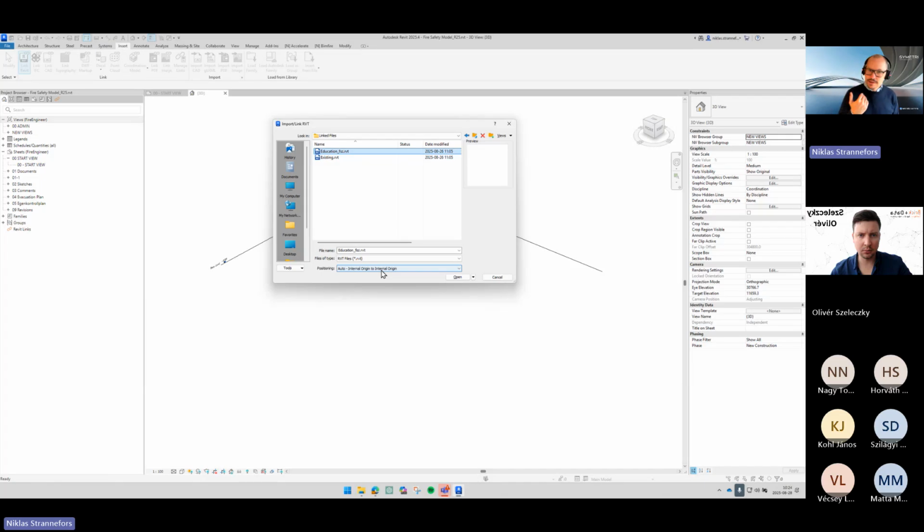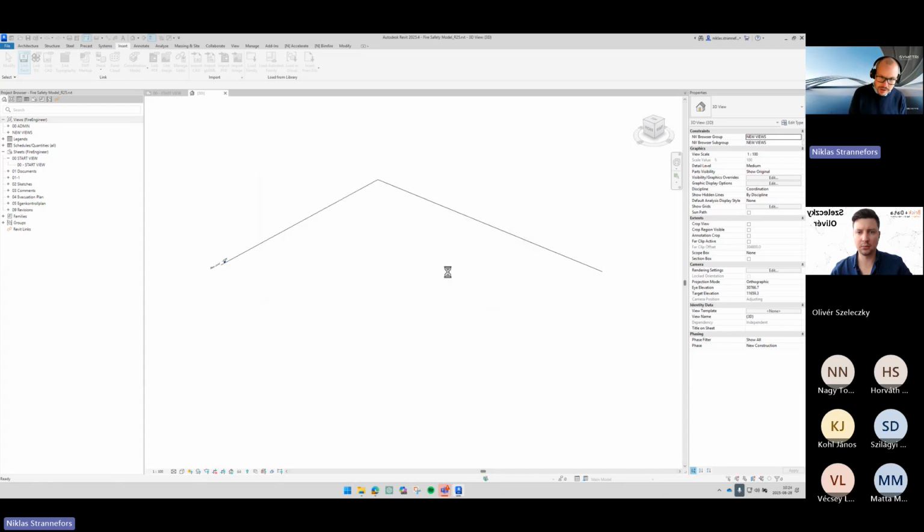If the architect has done something wrong, we will get the same error, so to speak, but we always do the same. We mimic the architect because they are leading the project. So there will be the same mistake everywhere, but it's easier. We follow them, they should do it correctly, we will follow, and it should be correct as well. Origin to origin always, and then we press open, and that will link the file. It's going to take a second or two to link it.